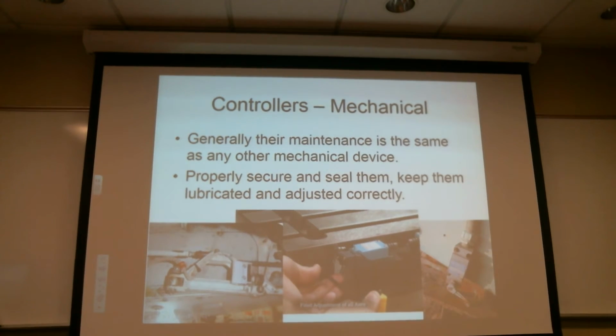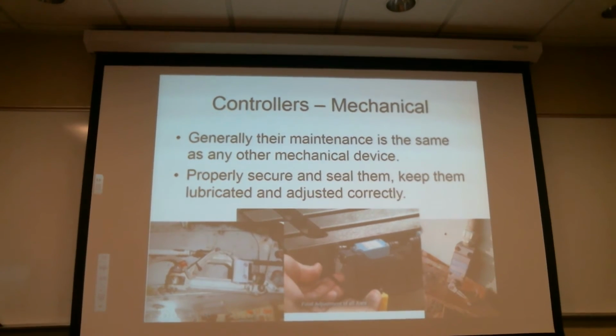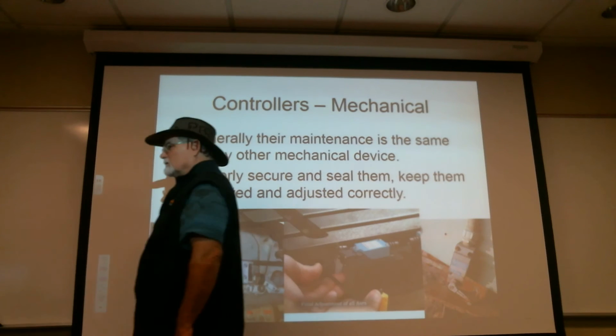The general service requirements for these things is the same as any other mechanical device. I know what you guys do all the time. You get in there, it says lube it up, you just lube it up. No, clean it. Get all the old grunge and grease and dirt and everything else off. Get it nice clean. Do any corrosion prevention or protection that needs to occur. Then properly lubricate it, adjust it, whatever the airframe manufacturer tells you to do. Or possibly engine manufacturer.